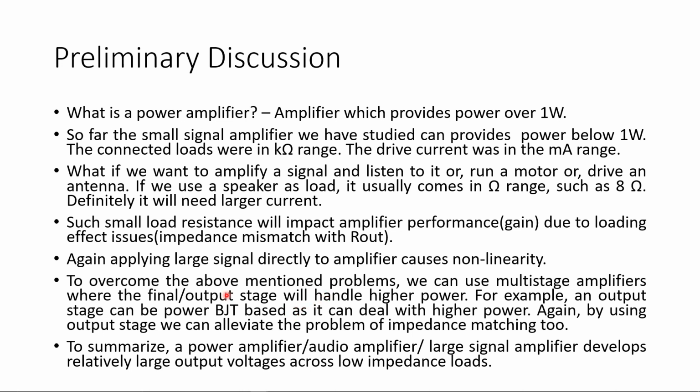Again, if we apply a large signal directly to the amplifier, we know that it will cause non-linearity. So the signal at the output won't be usable. That is another problem. These are some of the problems that we need to address. To overcome these problems, we use multi-stage amplifiers. Instead of using a single stage, we use multi-stage.